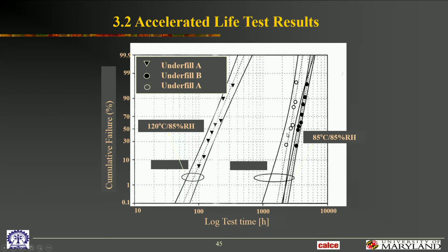This is just a zoom in of the data I just showed you. This is at 85-85. This is at 120-85. These are two different accelerated tests, because remember the use condition is only 35 degrees C. So both of these are accelerated stress tests.